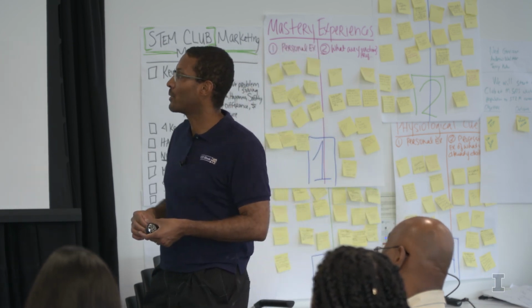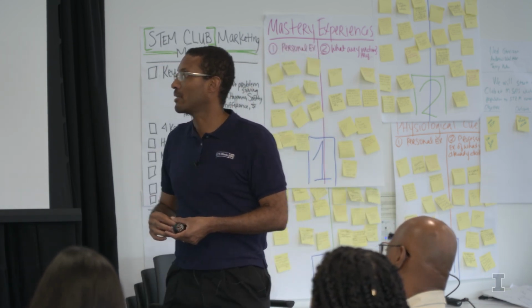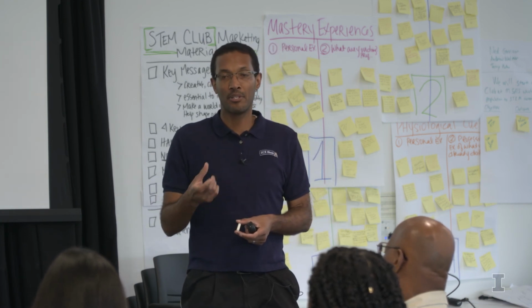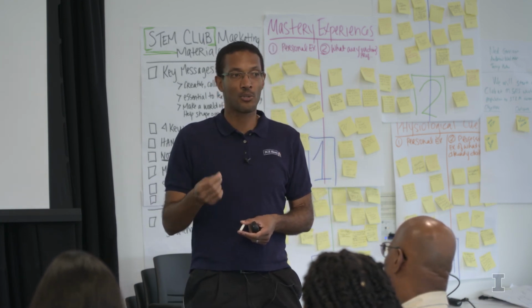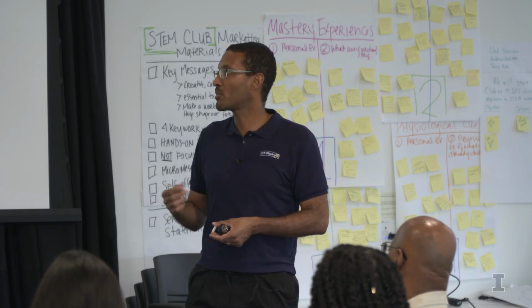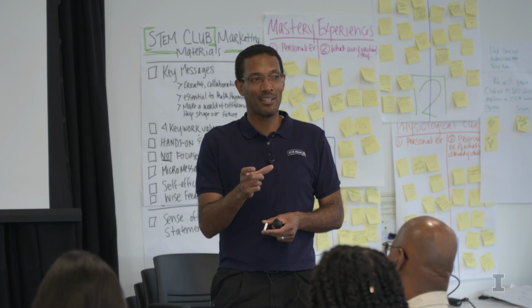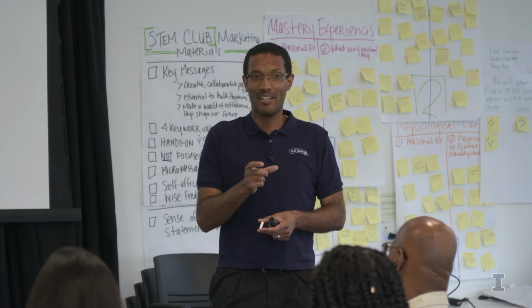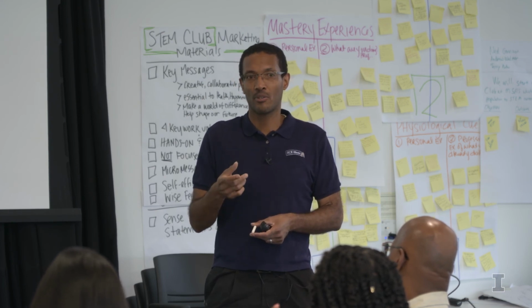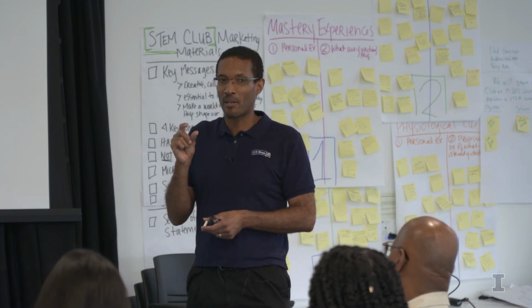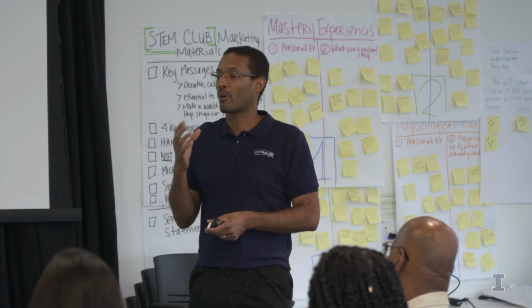Okay, the red LED will light up with either 1 or 2 AAs, but the blue LED needs 2 AAs. The reason is that the energy of the photon associated with red light corresponds to 1.9 electron volts. And so a 1.5 volt battery, well, it's less than 1.9, but it can still turn it on. There's enough energy that it can just barely turn it on. If I got up to 2 volts, it'll suddenly be very bright.